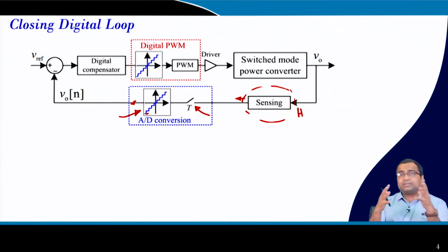So, depending upon different architecture, but in general for ADC we consider 2s complement. So, this kind of coding also needs to be considered, because accordingly the output binary number which is coming out of the ADC will be treated as either 2s complement or offset. If you do not take this coding into account, then you may completely misinterpret the data relative to the real world analog signal.